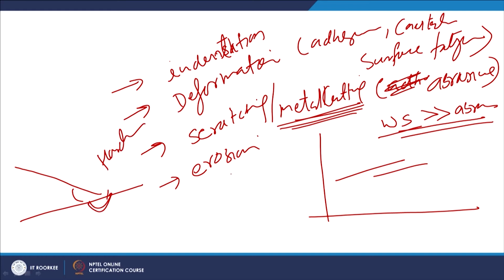While in case of high angle impingement, it is the brittleness that governs the material removal under erosive wear conditions, because at 90 degrees it causes the maximum metal removal rate by the erosive wear mechanism. So, it is preferred that hardness is somewhat lower when the impingement is taking place at 90 degrees, while the hardness is high when the impingement is taking place at a low angle.